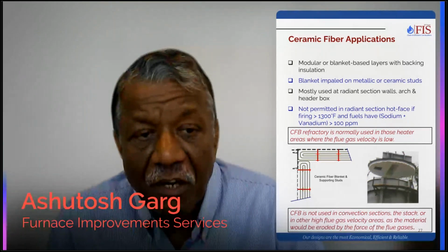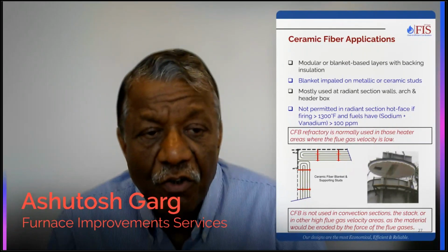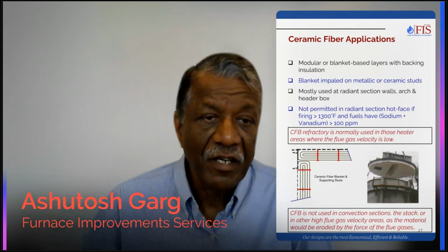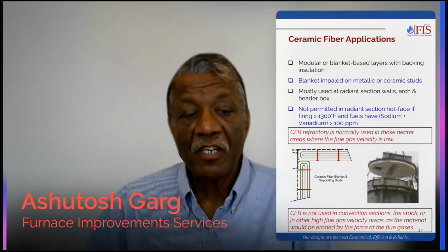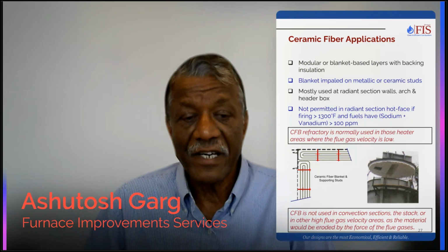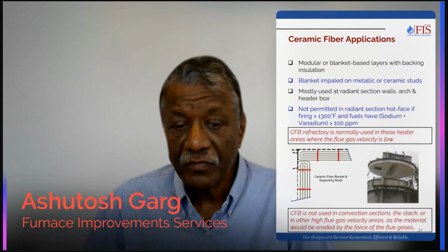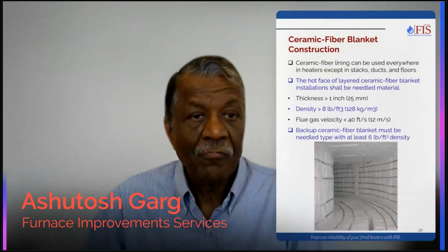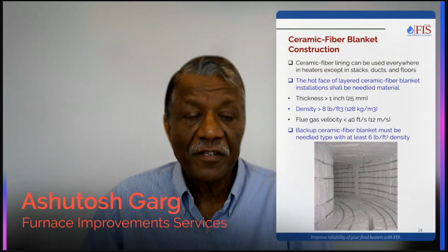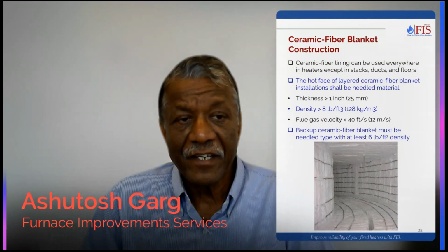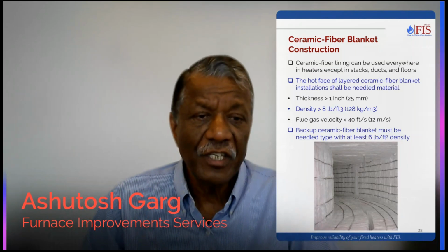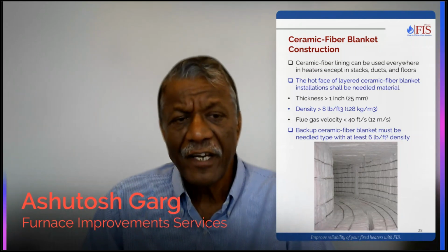So one of the downsides you can see is it's not good for heaters which have sodium or sodium plus vanadium, which starts getting fluxed. It's also not good in convection section stacks or ducting. But other than that, it's very nice. As I said, 1 inch layer is the standard thickness of this. And density is 8 pounds. It's available in 3 or 4 densities. 8 pound is very common.